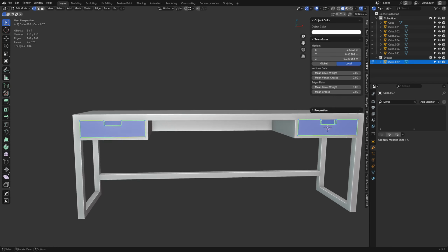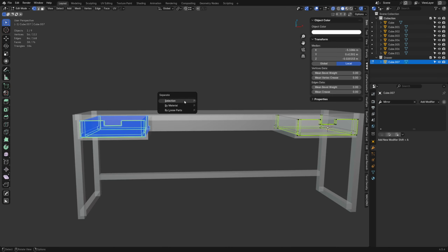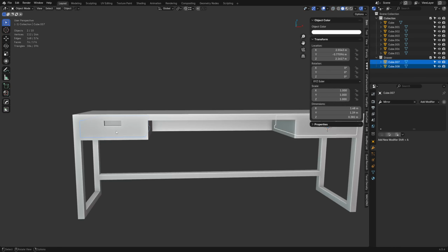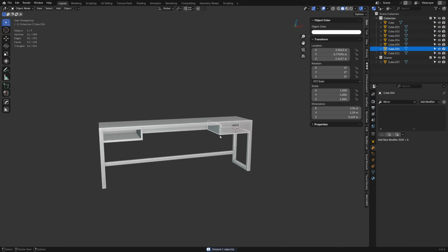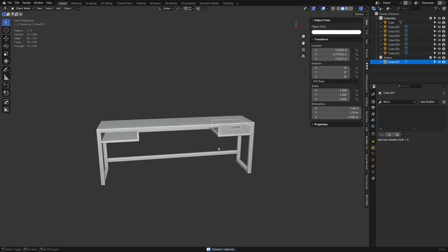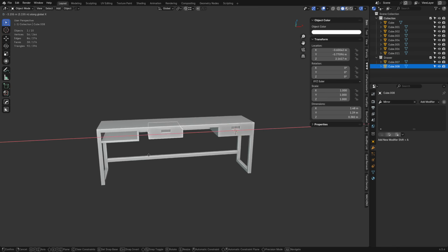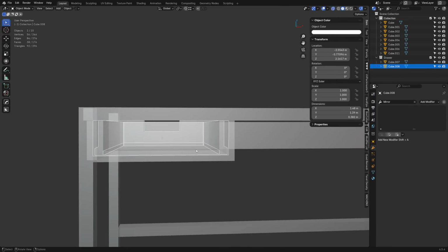And so we can apply the mirror. We can grab this object over here. We don't necessarily have to separate it either, but I think it'd be better if we did. So separate the selection. The only downside of this setup is we lost the origin point. Sometimes you want to do things like this, sometimes you don't. It's really up to you. For me anyways, I'd rather just duplicate it over, make sure I got the right x-axis here and set it negative. And then if I need to, invert it or something, which I think we might have to.